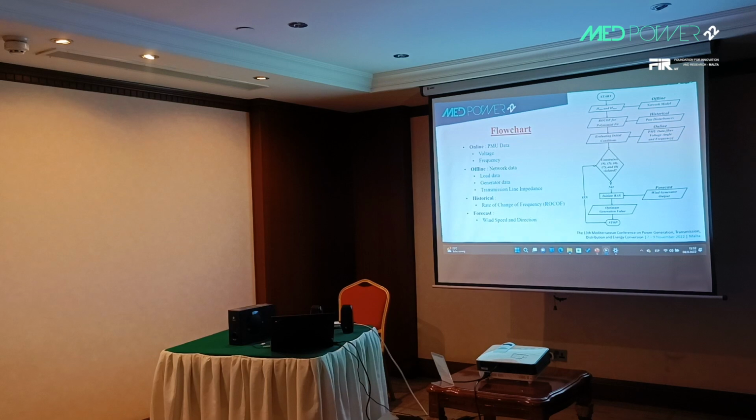If any of the constraints listed from 4 to 8 are violated, then the remedial action scheme will not trigger because the basic constraints for the power system are being violated. If and only if the constraints from 4 to 8 are not violated, the remedial action scheme will be initiated and the optimum generation value from the wind power generator will be calculated, and for that specific network inertia, the maximum wind power generation will be obtained.